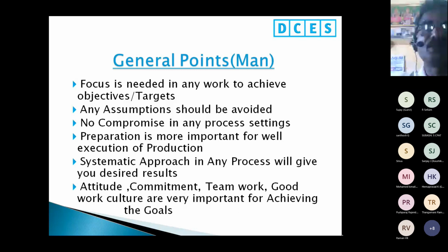And preparation is more important for early execution of the production. Preparation means that before the start of production, especially in high pressure die casting, everything should be properly kept near the machine. For example, after the start of the first shot, the operator is always wandering or searching for ladle coating, ladle cup, etc. This should be avoided. Otherwise, what will happen? By that time the die will cool down. So a systematic approach in any process will give you the desired result. Any process should be followed as per the written statements.